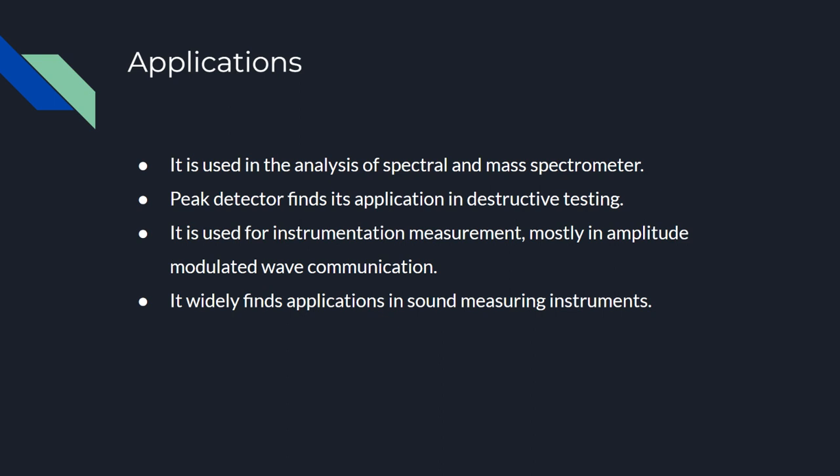It is especially useful in applications where a fast and accurate measurement of the peak value of an input signal is required. The performance of an op-amp peak detector can be optimized by selecting the appropriate values for its components such as its reference voltage, its load resistor, and its storage capacitor.